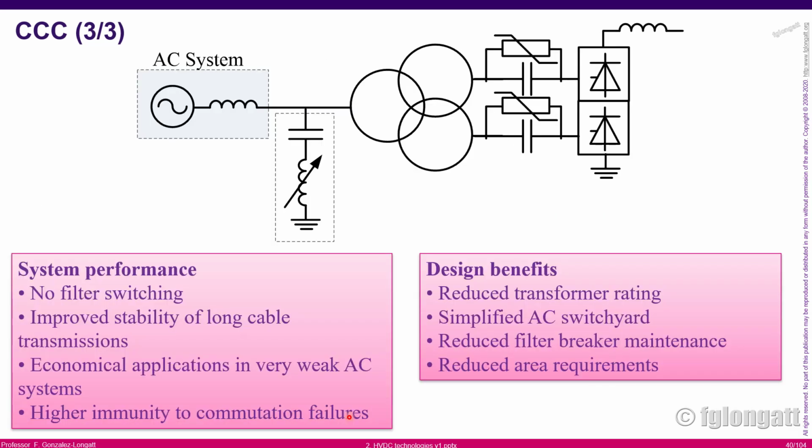There are many benefits over here. The filters that we require on the AC side beyond the commutation transformer are smaller, or probably you don't need those filters at all. And to be honest, if we are using long cables to supply the electricity to those transformers or going into the converter, that also improves the stability.